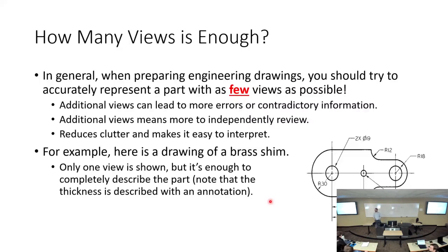It's easier to measure in real life. Just holding up a ruler across the whole thing versus trying to find the midpoint. You're really close. You're not wrong, but let me ask you this. Let's say this was a piece of wood. How are you going to fabricate this? You're going to cut the board out, but then to cut this hole, what are you going to do? A 2-inch jigsaw. You're going to drill, right? We tend to specify holes in diameters because that's how you spec out drill bits. That's pretty much it. A lot of the reasons for that just go back to the real world.